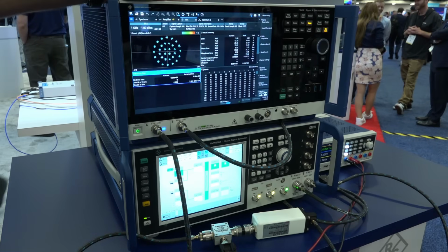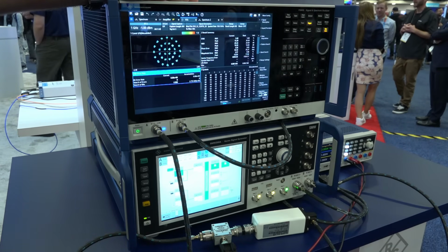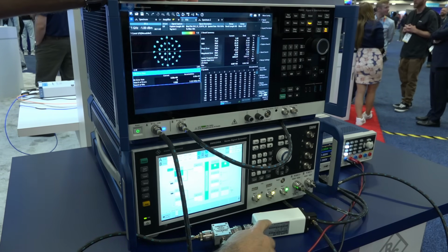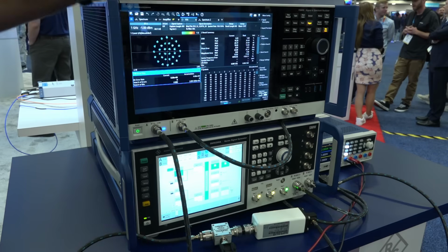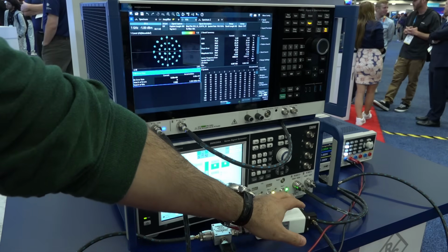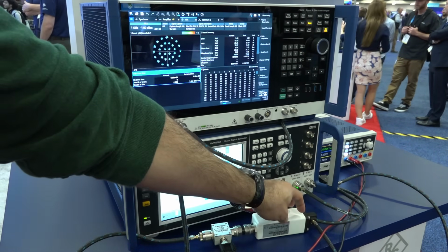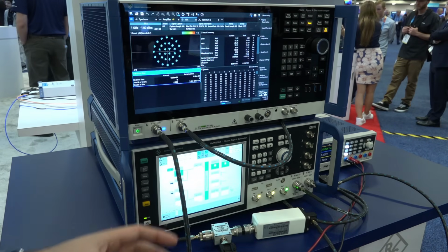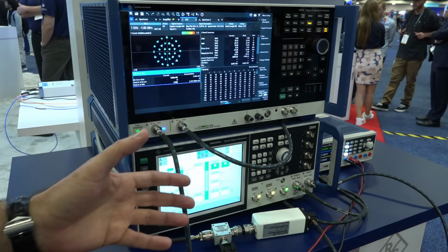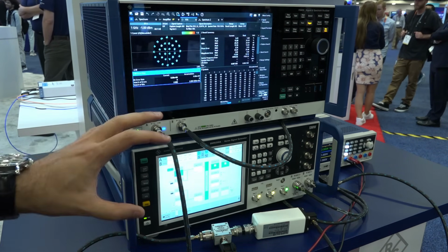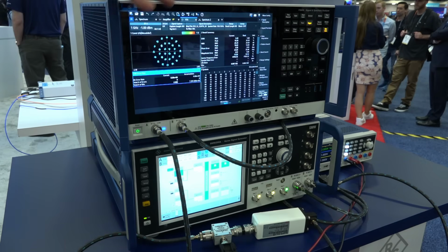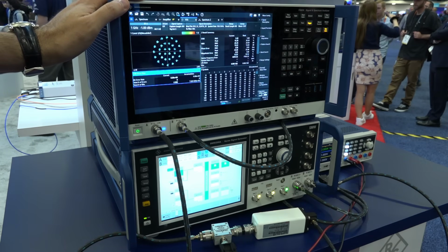So here's a live measurement showing something that is very difficult to measure otherwise. So here we have a satellite device, which is actually a frequency converter. So we have a different frequency at the input, and after this, it's essentially a mixer. Now imagine that you want to characterize this mixer's nonlinearities, its imperfections, and its dynamic behavior under actual situations when it's transmitting a modulation, in this case a PSK, particularly for satellite. So how would you do that?